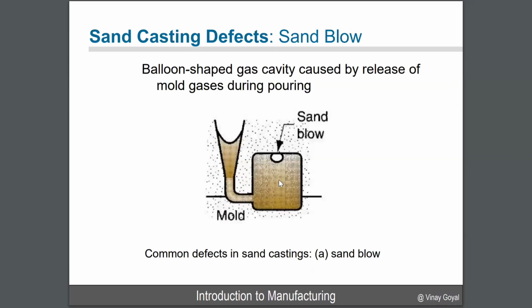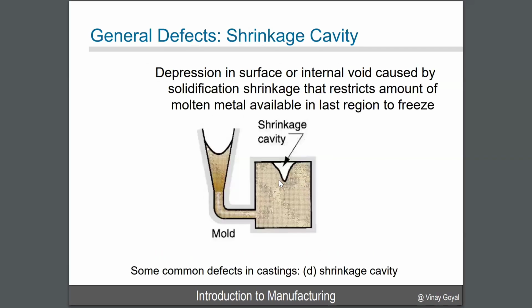When it comes to sand blow, it will be very obvious on the surface. There are approaches to either sand that out, or you can use new techniques now that spray metal on that surface to kind of seal it off. Is that helpful? Yeah. Let's keep going.